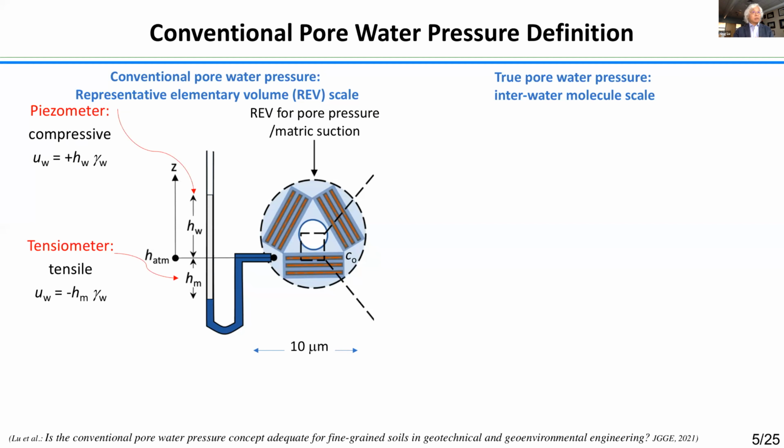But you can measure in the situation where the larger pore has experienced lower than atmospheric pressure. From there, you can calculate what the suction would be. We no longer call it pressure, commonly it is called suction, which is physically the same thing as the compressive pressure we talk about.